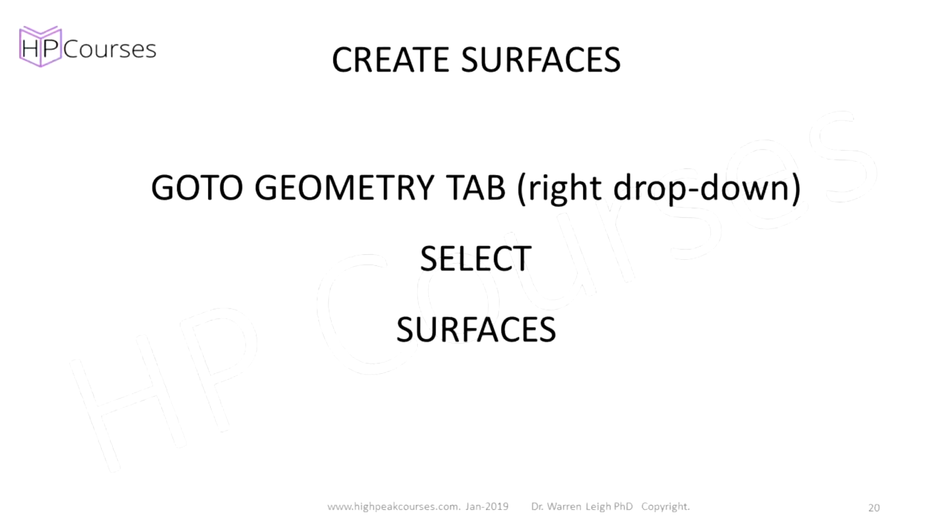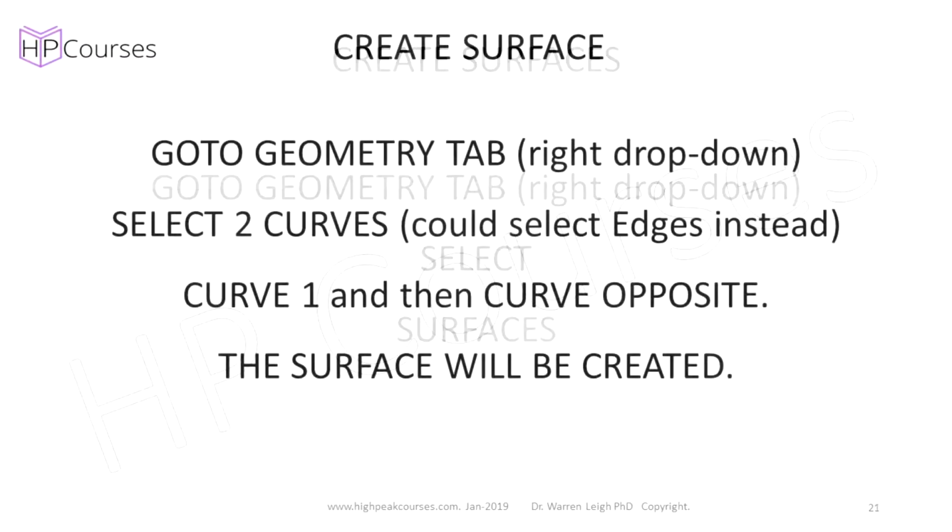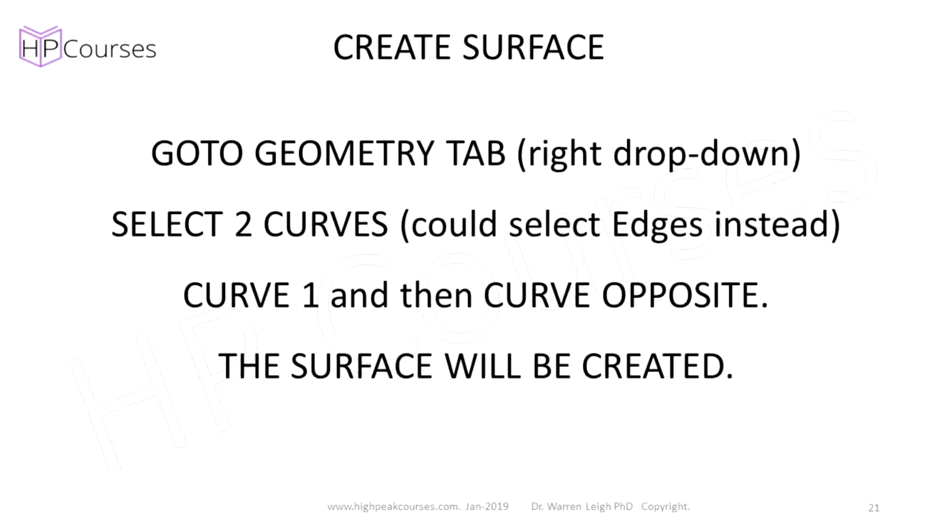To create the surface, in the upper right drop-down box, select Surface. Choose either the 2 or 4 curve method.